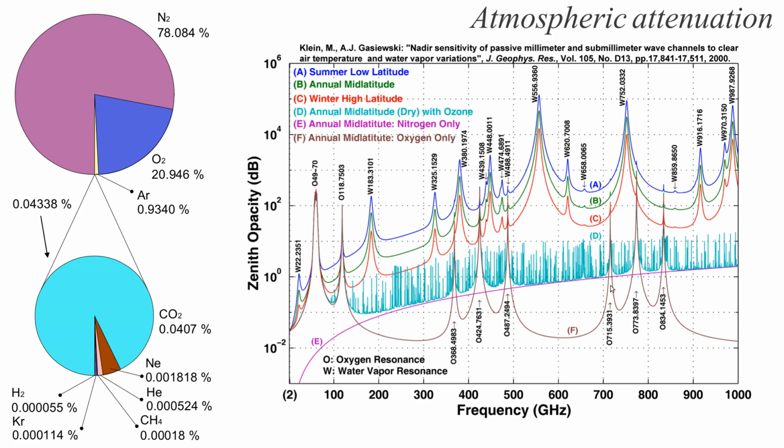Nitrogen is almost unimportant. Ozone is somewhat important. If we cross the ozone layer, say for space communication, then ozone becomes a problem. So we can no longer consider the atmosphere to be transparent above 100 GHz. Below 100 GHz, there are pretty wide ranges that are still useful, but above 100 GHz, the atmosphere is no longer transparent.